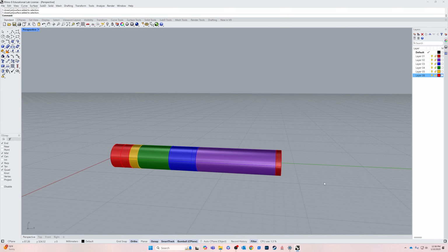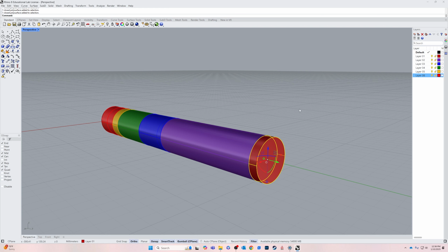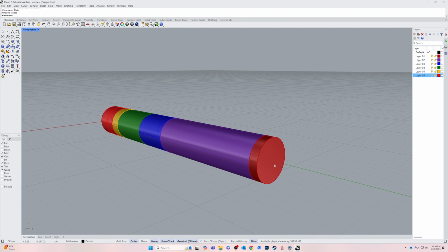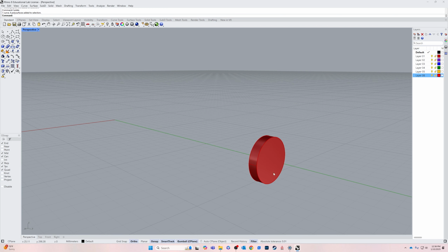So I'm going to click on this object, and then I'm going to do my center mouse wheel click. So again, we need to make sure we're using a 3-button mouse. It's always much better for any CAD-based program to have a 3-button mouse. And then I click on the light bulb and hold it down and go to isolate objects. Okay, subsequently, you can also click on it and type isolate, and that works too.